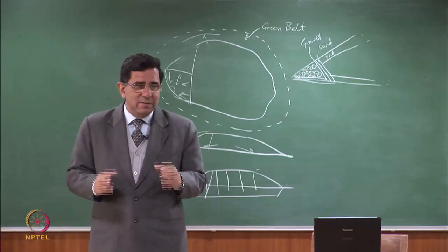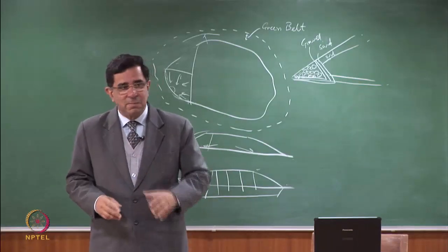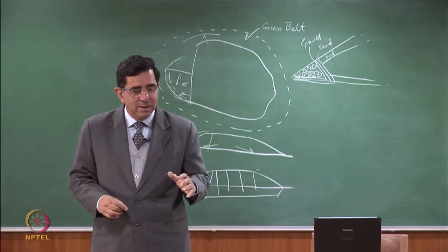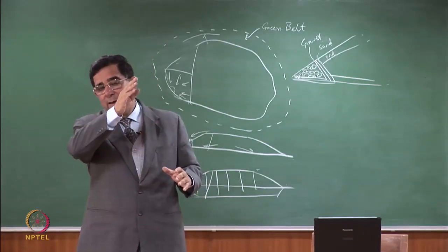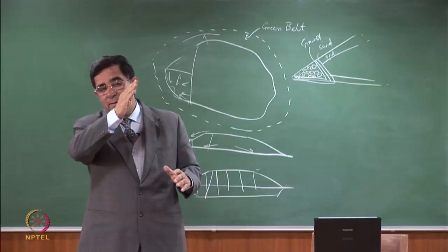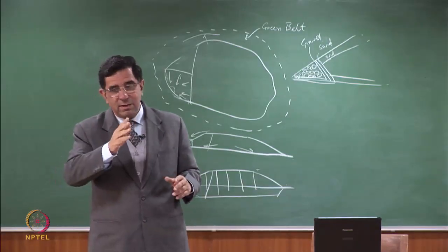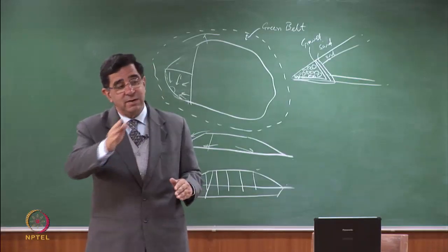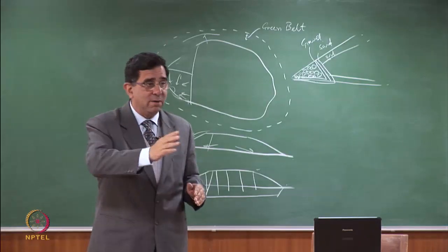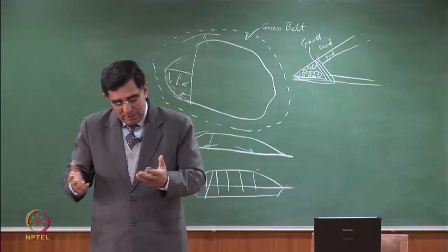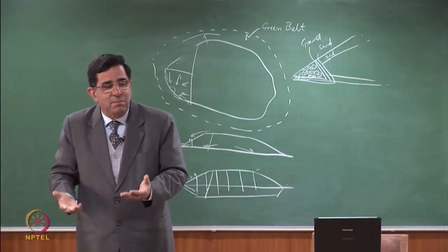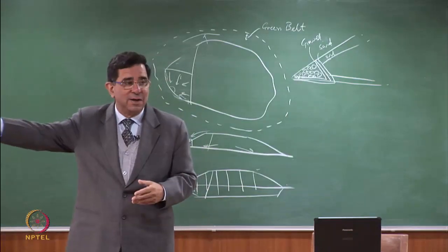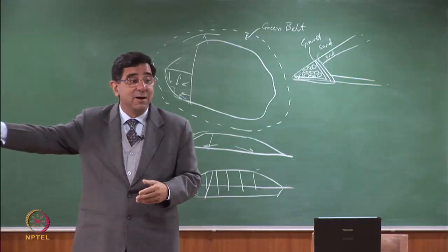So if you go to a well-designed landfill, this is what you will see. Green vegetation on the closed part. The intermediate cover will have soil on it, and if you are conscious that monsoons should not affect it, some people will also have a temporary tarpaulin or a temporary cover on the intermediate cover. And you will see the landfill rising up in the active phase, and you will find some machinery working in another phase which is under development.